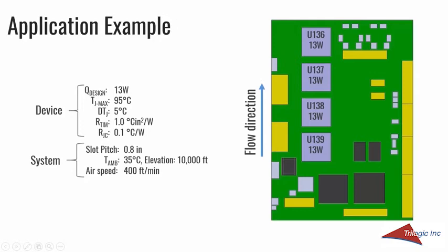It did have one interesting constraint: to try and maintain these component temperatures within 5 degrees C of each other. That has to do with the operation of the board, the timing of these ICs. And we see the interface material is 1 degree C inch squared per watt. In the previous example, I used the same interface material because it's low power.